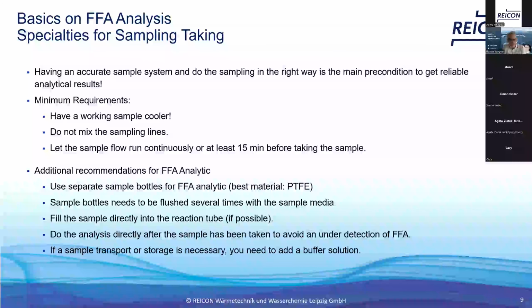Or, if it's possible, take the sample directly in the reaction tube so that you can do the analysis immediately, because the longer the sample solution is stored in the bottle, the lower the concentration you can detect in the sample.